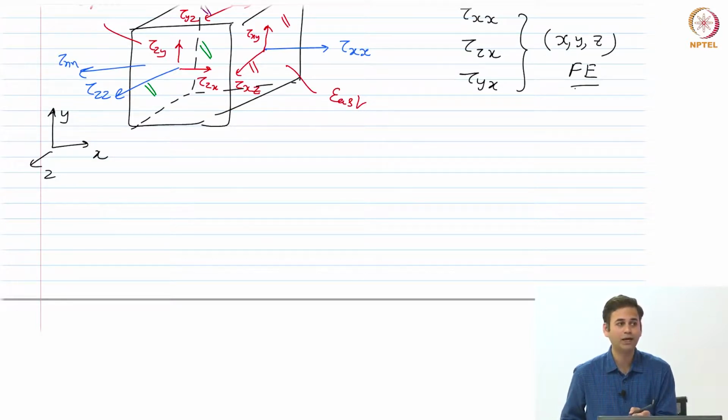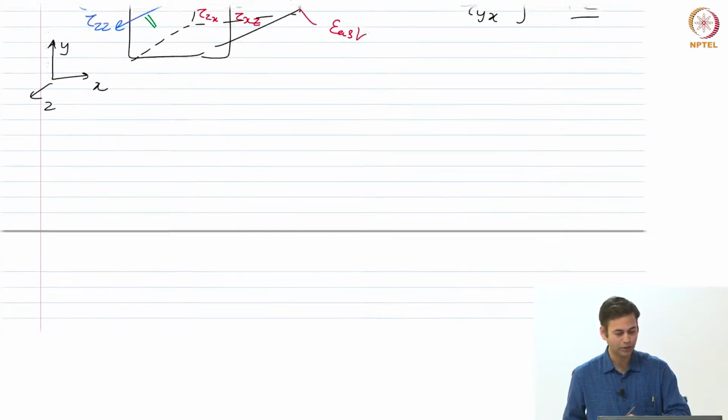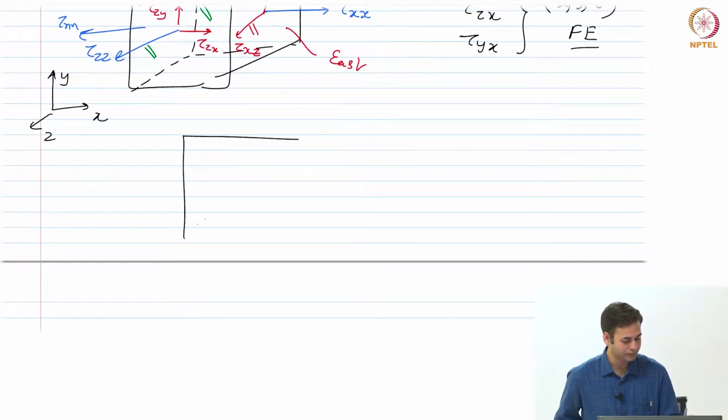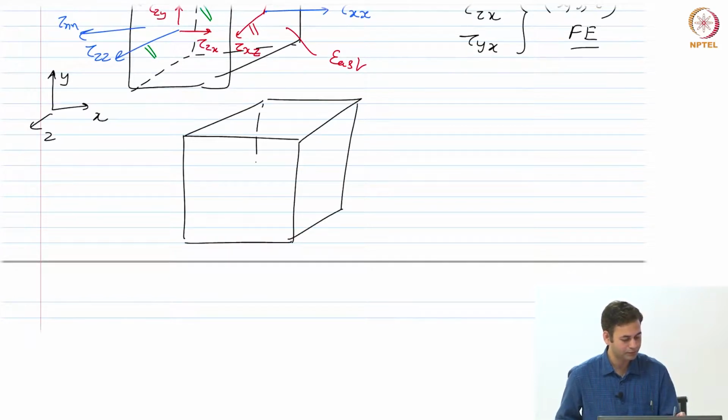Now, we have to again use Taylor series expansion if we were to draw them on the fluid element faces. Here, only to represent the state of stress, I have drawn it on the surfaces, but I will go back to my original fluid element that we have used in the definition of the conservation of mass. So, I am redrawing this figure in our original way, where the shear stresses or the properties are all defined at the centroid. So this is the centroid, which is x, y, z, and I have tau xx defined at the centroid of this fluid element.